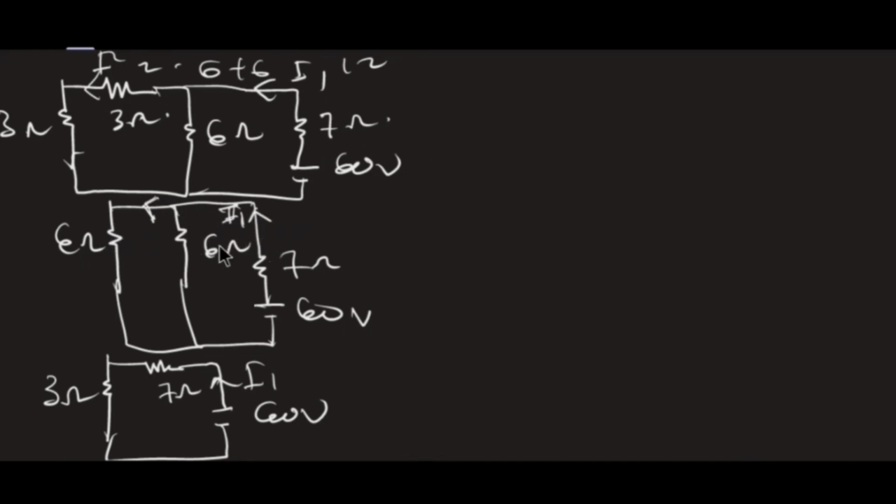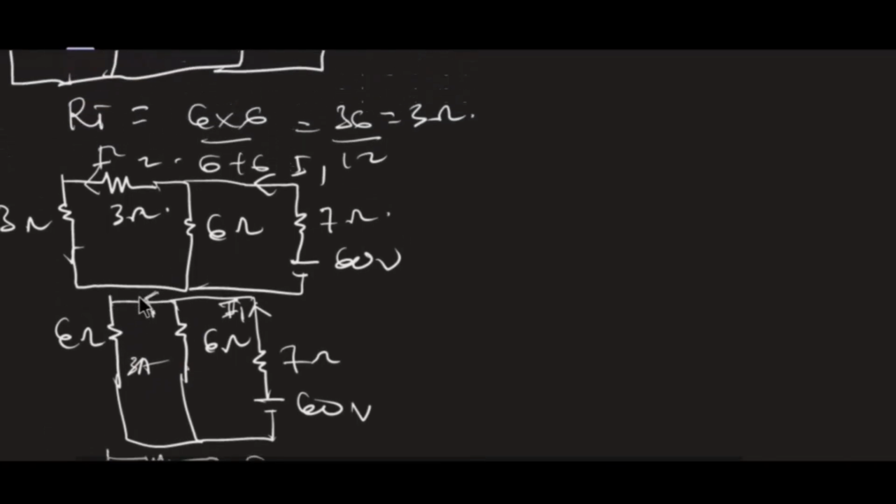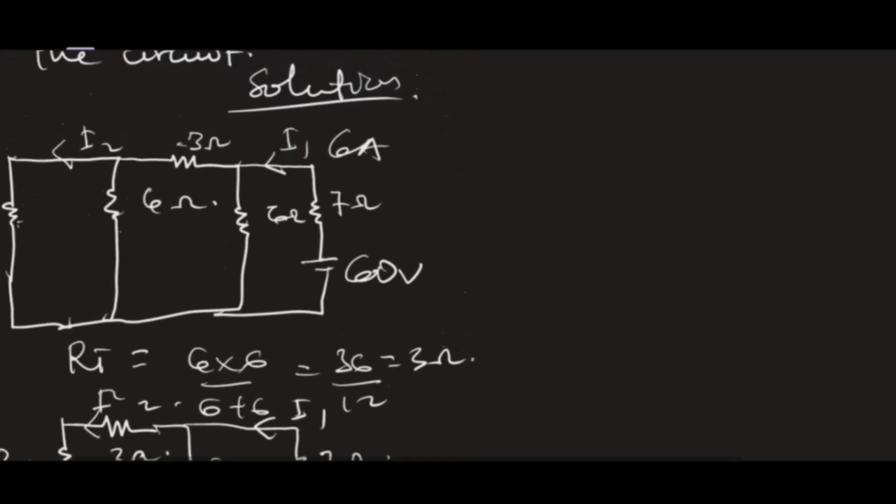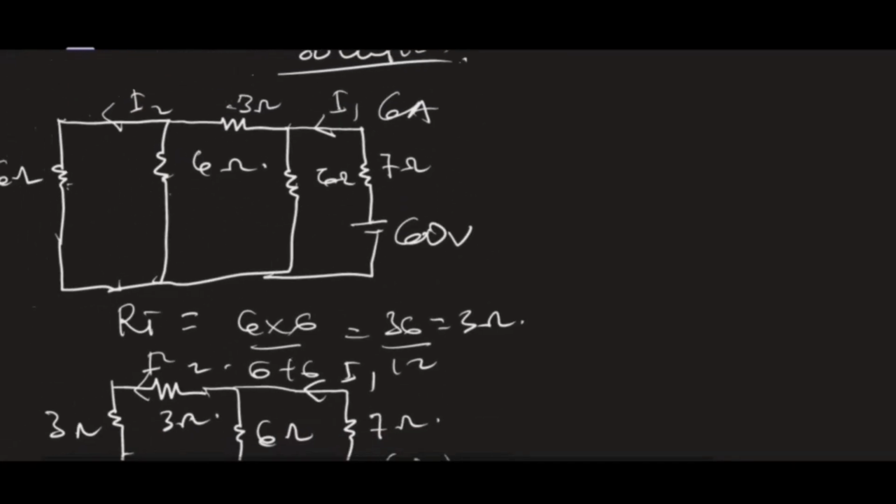I have 6 amperes, so since they are equal, I'll have 3 ampere going here, then 3 amperes coming here. So now I've got 3 amperes coming to this 6 ohm. And you know that this 6 ohm is a combination of this side to this side. For that reason, the current has been able to pass through this. So at this point, you realize that this whole combination was 6 ohm and the current passing through is what? 3 amperes. So the 3 amperes will pass through these 3 ohms which is direct in series.